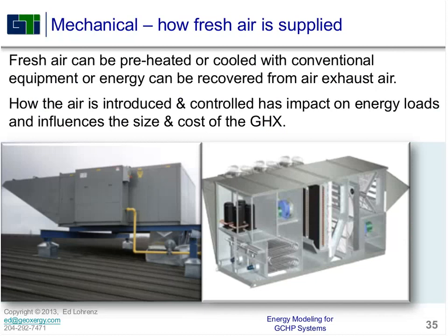You can look at using gas rooftop units, for example, or heat recovery ventilation or energy recovery ventilation. In some cases, especially in northern climates, in order to balance the loads, it may be better to put in a gas rooftop unit rather than a gas boiler to supplement the system. And you can often make a building that would normally be heating dominant work if you tried to do this with a geothermal system.